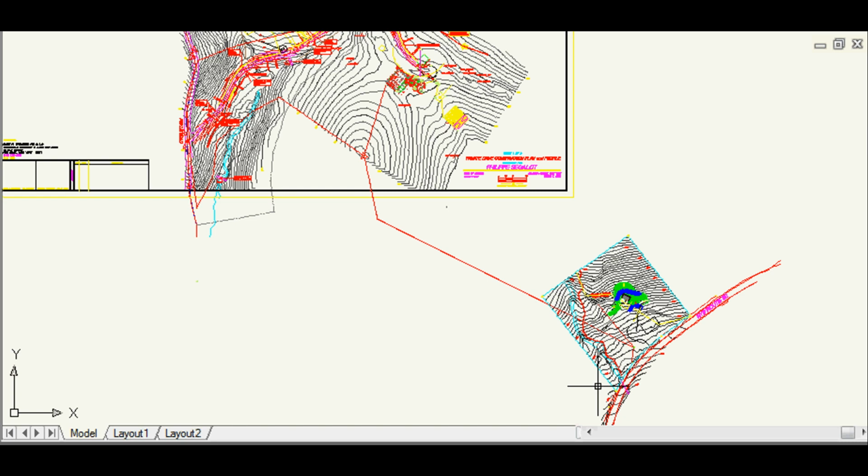Well, there's a couple different ways. There's something called RTK, which is real-time kinematics, and that's where you have a local GPS station collecting data, and you correspond your field data to that, and you crunch that math down to get high-quality resolution of elevation. And then there's another way to do it, a little bit different. It's a similar setup, but you're using a station in Albany, and they collect data all the time, and then you download your data, and then you have reference data to go against. And because it's further apart from where you are, that goes back to that rotation thing, it actually gives you a better resolution. All right, so that's just basic information.